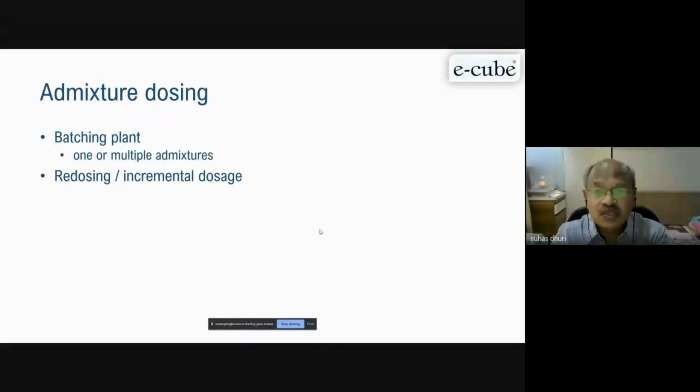Those things one has to see whenever recommending for the plant, and the plant also has a sequence of mixing. As I discussed, the sequence of mixing is very, very important in concrete to get better strength with effective and optimum admixture content and cementitious system. Otherwise, you will end up with a very high amount of cement system and admixture for the same performance. So you must note down, mixing is very important in concrete for particular admixtures.